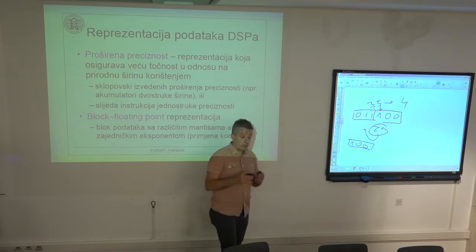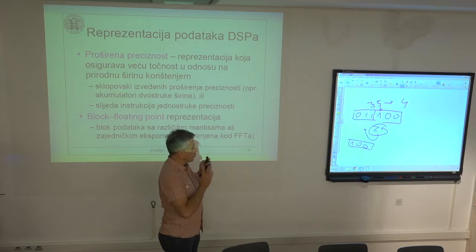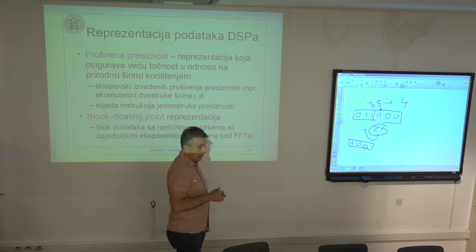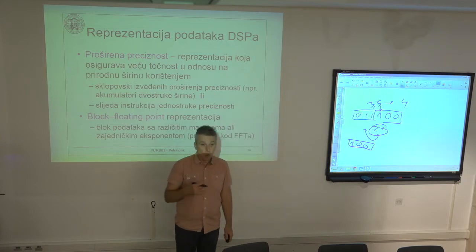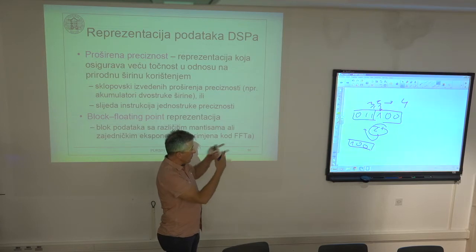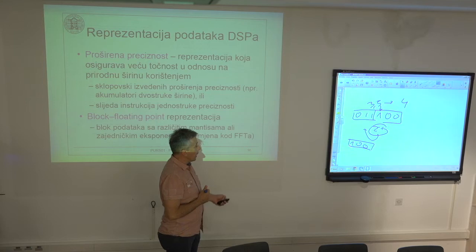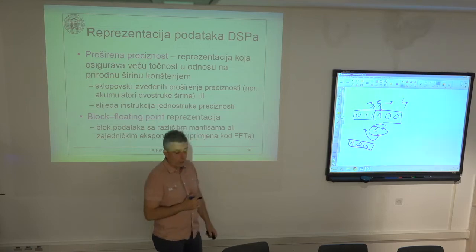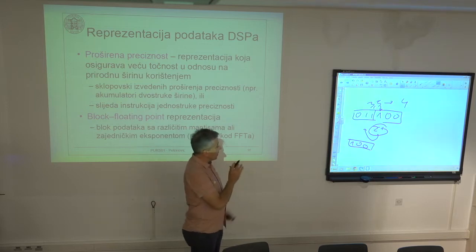And there is special hardware in the DSP that takes care of this, and it would not allow this to happen. If the result of a rounding operation or addition or whatever causes overflow and this kind of wraparound, where a positive value becomes negative, it will automatically saturate this value to the largest positive value. We will discuss this separately. Nevertheless, we can understand this operation of rounding.